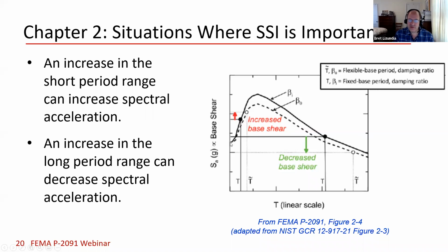So we start at sort of the equivalent soil peak ground acceleration at 0 period, and then we dynamically amplify up to the plateau. This sort of traditionally is maybe around a half to 1 second, depends on your site class, of course. But as you get up there, if we have period lengthening.